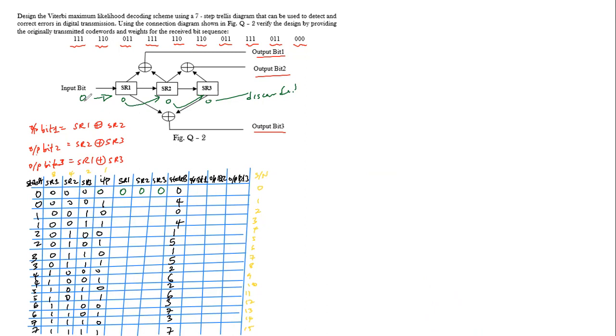If we feed in an input 1, when that 1 comes in here, this 0 moves to this, and the 0 that was held originally moves to this, and then the 0 held originally here is discarded. So we now have our input 1 here.